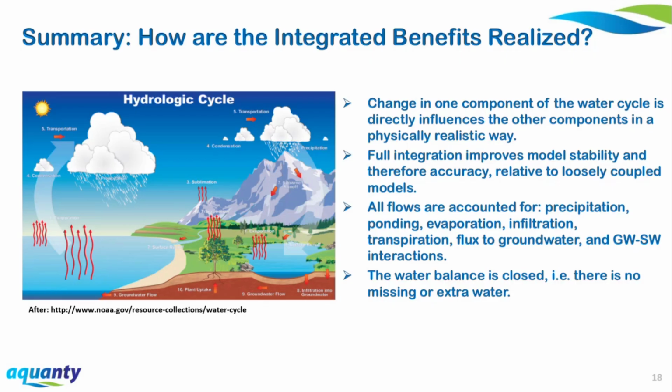So in conclusion, the value proposition for using an integrated hydrologic model is really that raining on a model and letting the water flow where the physics dictates is conceptually easier in deciding where and when recharge and discharge will occur. HGS itself is particularly applicable to shallow groundwater flow processes, such as classic groundwater surface water interaction problems. But overall, a more integrated approach helps model users make better informed decisions that are now commonly required components of groundwater and surface water projects.